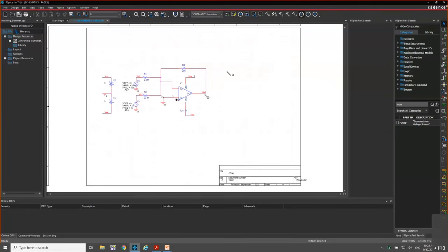So we're going to look at Vout, we're going to look at VIN2 and VIN1. It's important to place the voltage markers after you create the simulation profile because otherwise it'll clear them when you create a new simulation profile, because it saves the markers between simulations. Now we're going to go up here to run, and the PSpice simulation window will pop up here.